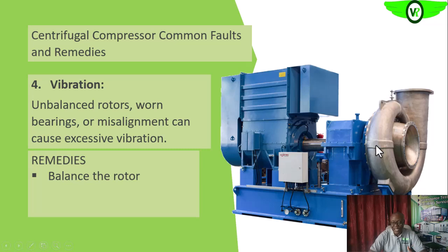If it is the impeller, we will also see it on the measurement we took at the compressor end. If the unbalanced forces is on the rotor this way, we will also see it. It is vibration analysis that will assist us in seeing the problem as it's developing, and then eventually taking care of the problem.